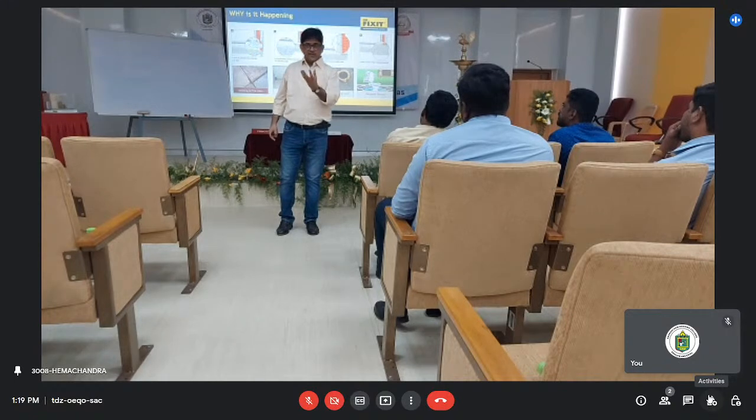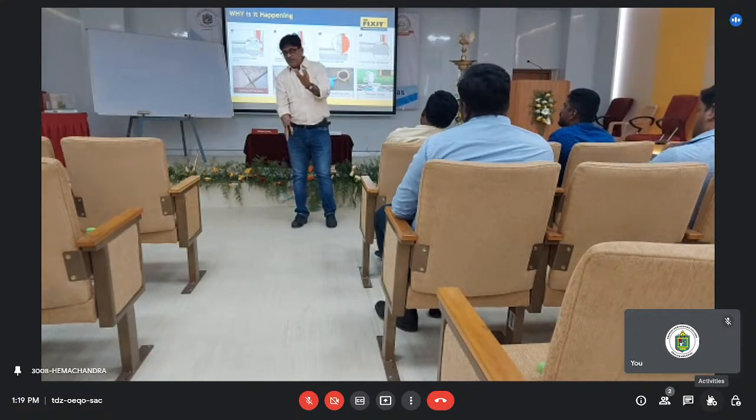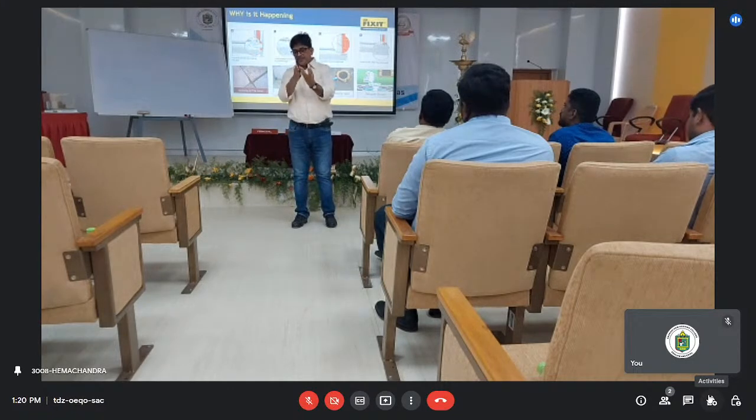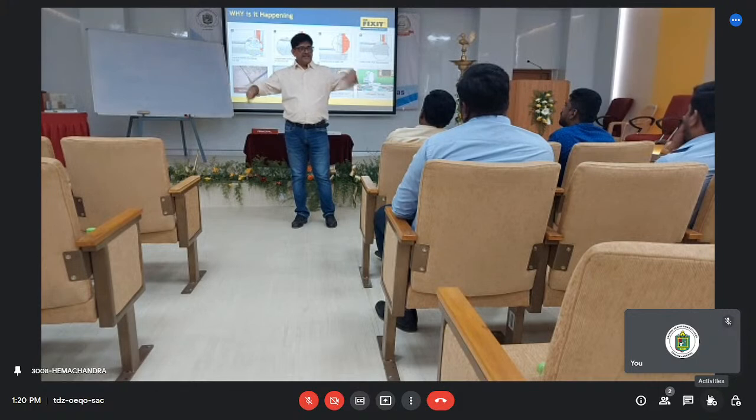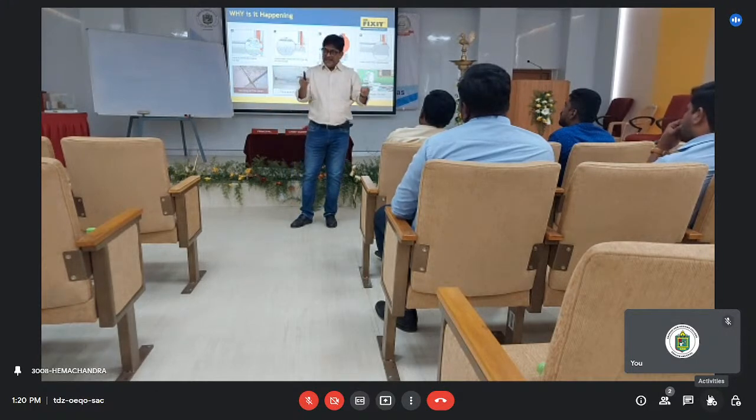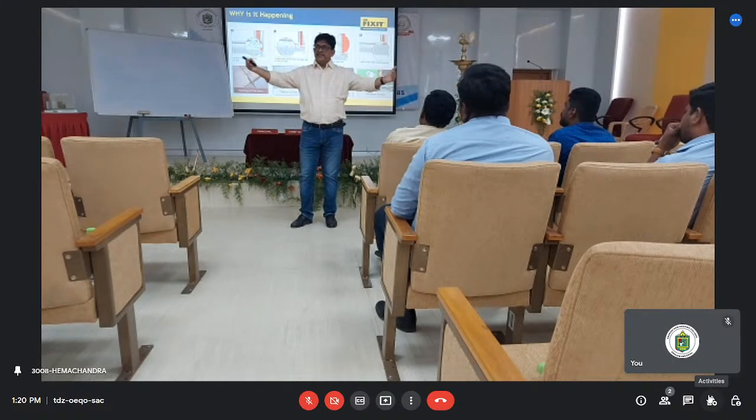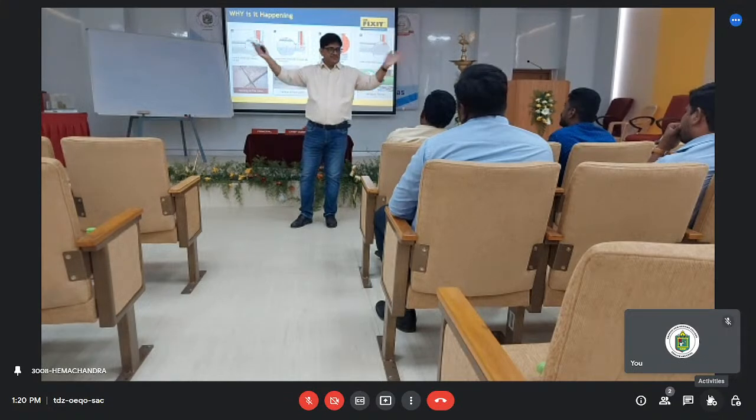So now we are talking about the remedial waterproofing repairs. Once it gets eroded, the water will start percolating. That water will either reach the baseline, or sometimes it may reach your base concrete. If it is a non-sunk portion, at floor level it starts moving, even through the tile joints or the cracks in the tiles, it reaches the concrete base. Then it starts moving horizontally, and at the wall level it starts showing.